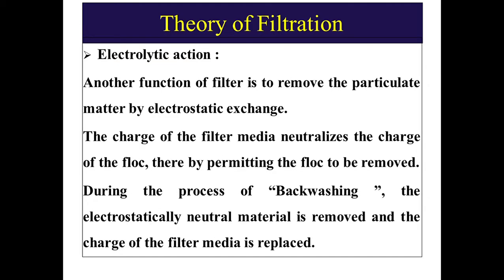And last is electrolytic action. Another function of the filter is to remove the particulate matter by electrostatic exchange. The charge of the filter media neutralizes the charge of the flock, thereby permitting the flock to be removed. During the process of backwashing, the electrostatically neutral material is removed and the charge of the filter media is replaced.